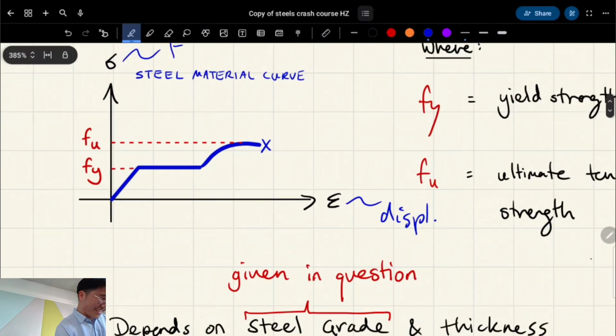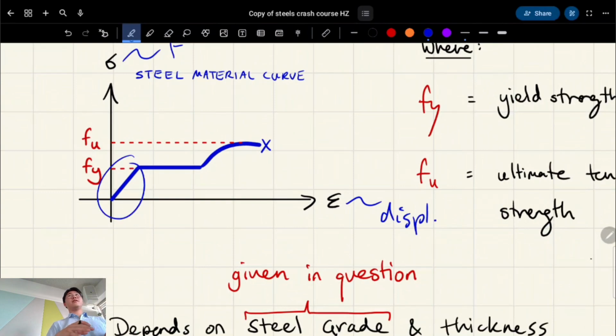I like it. Okay, let me repeat that. So this first stage, steel behaves elastically. This is the elastic region. That means if I had an elastic band and I'm stretching it, and then I let go, it's going to return to the exact same shape that I started with, hence the name. So that's elastic behavior. It's where there's no permanent deformation. Steel does that for a little bit, and then it plateaus. So why do you guys reckon it might plateau?